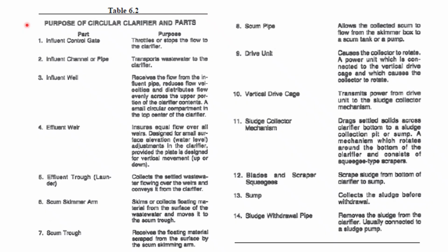One favorite that they ask about is what causes an uneven sludge blanket, or what are the indications of an uneven sludge blanket. Those are things you should be able to look at, including the torque indicator up on the catwalk for the motor that's moving that sludge rake around. Please do take a look at this and match it up with the diagram on the previous page. You will get a few questions here and there on your different levels.